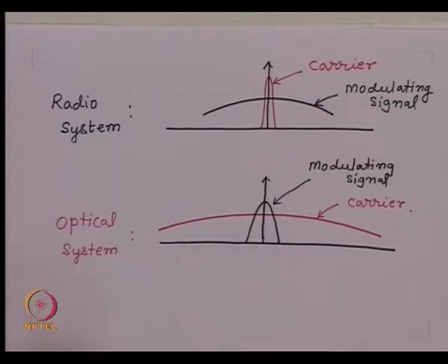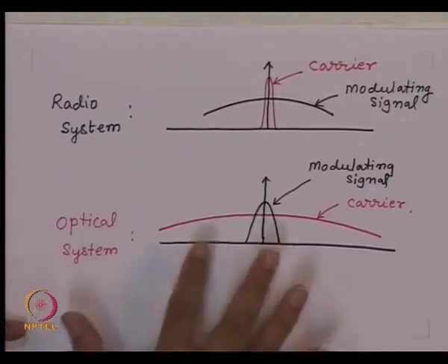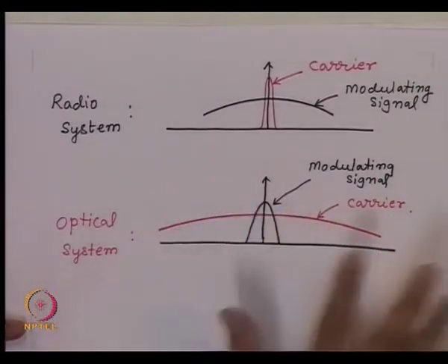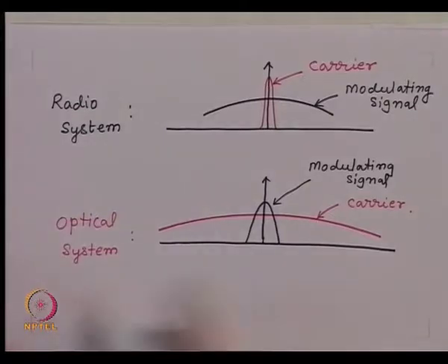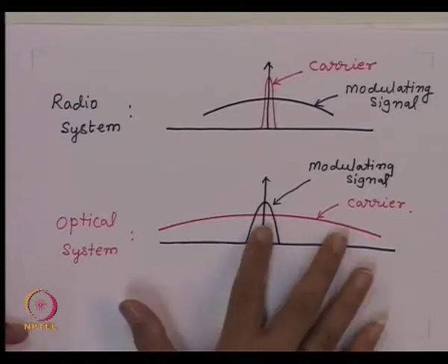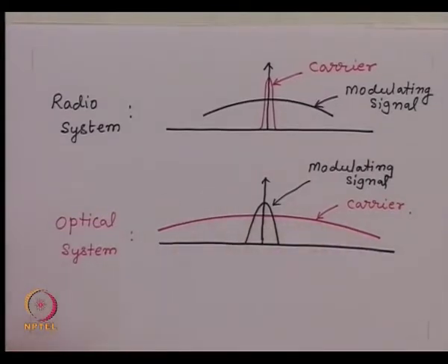then the total spectrum will be nothing but the convolution of these two. So the total spectrum will be more or less identical to the spectrum of the carrier. It will get modified, but this modification will be very marginal. So whether we modulate the carrier or don't modulate the carrier, you will see the spectrum which will be the same as the carrier spectrum. Or in other words, what that means is that there is no clear signature of modulation in the spectral domain for an optical system.